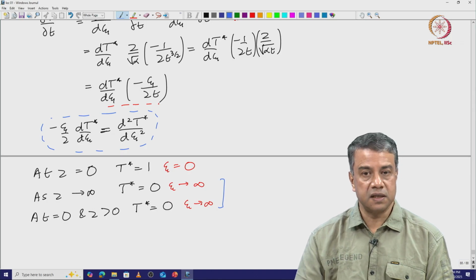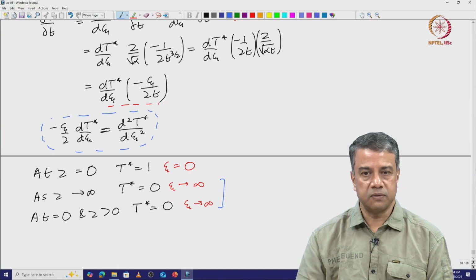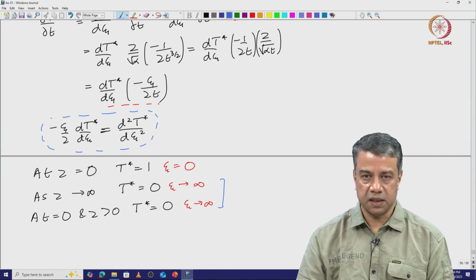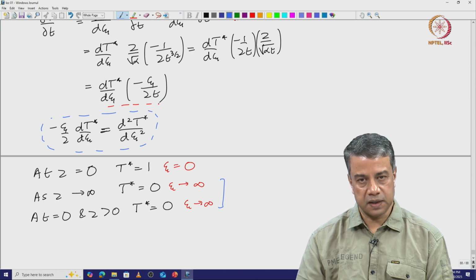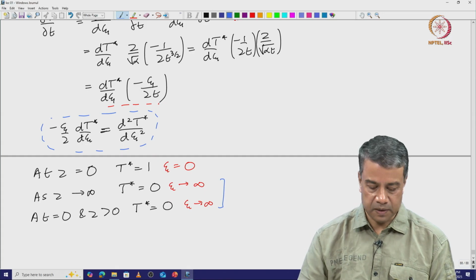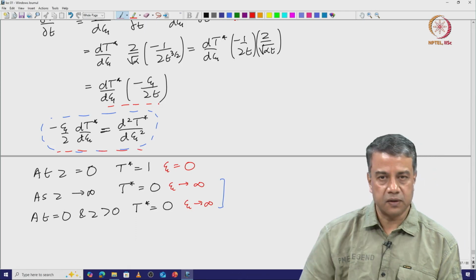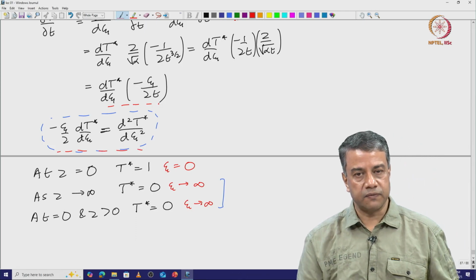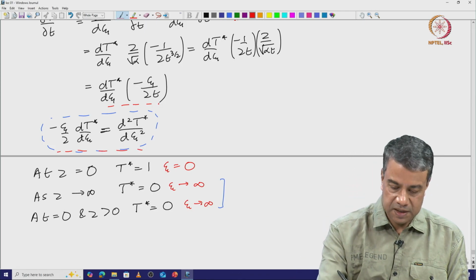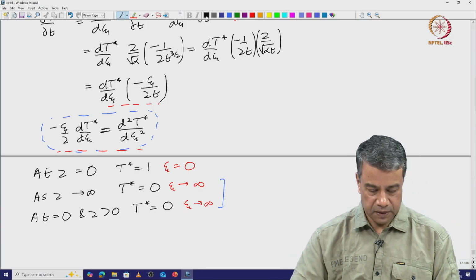And it is necessary for them to reduce, because the original equation had first derivative with respect to time, second derivative with respect to z. You needed two boundary conditions, one initial condition. The transformed equation in terms of the similarity variable contains only a second order equation for psi, and therefore, you can have only two boundary conditions in the psi coordinate.